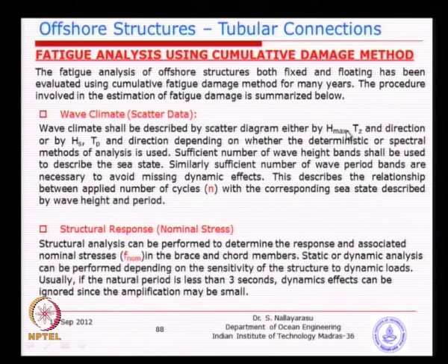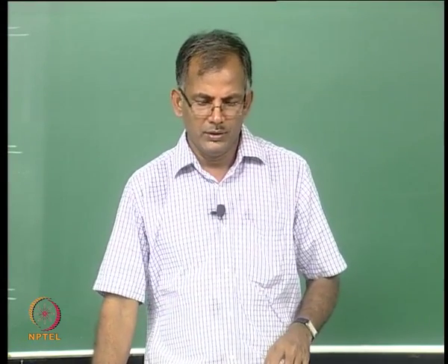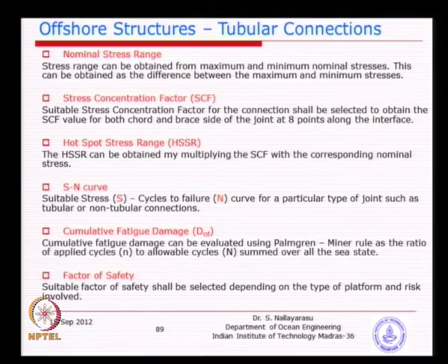We normally use the first one for simplified fatigue, basically using the deterministic analysis, whereas the spectral response will use the significant wave height and the corresponding peak period. Let us learn how easy it is to do this method first, then we will go to the response by spectral. In doing so, there are several things you need to work out.